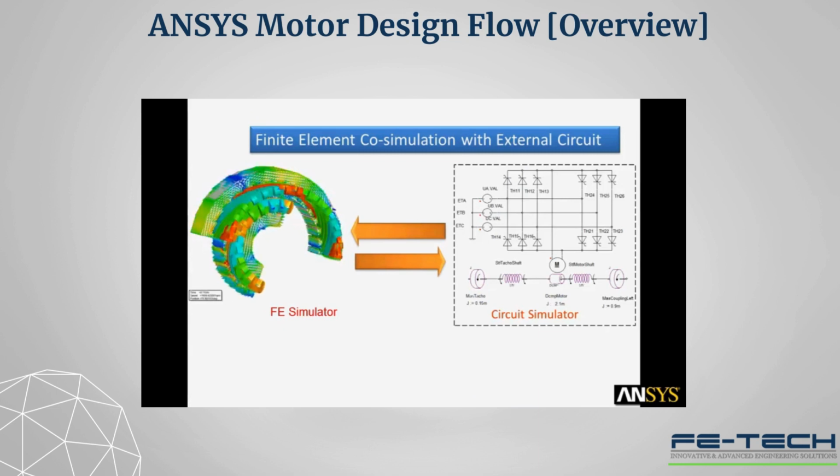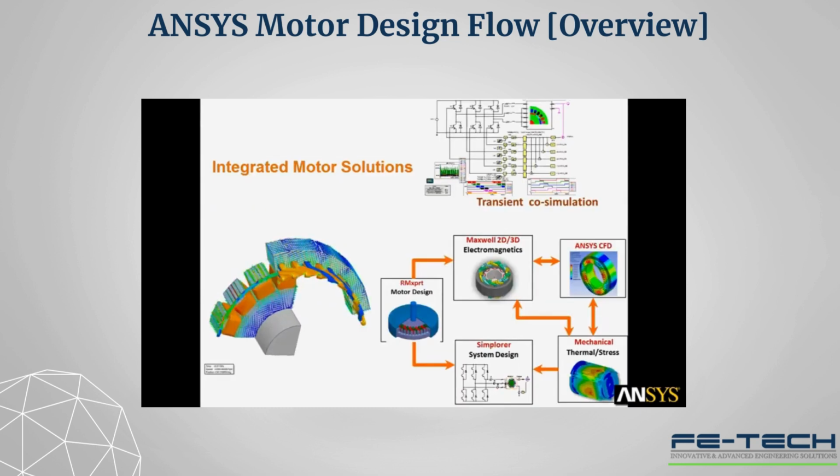Electric machines require appropriate electric drive circuits. Maxwell finite element analysis co-simulates with the Simplorer circuit simulator to evaluate how nonlinear behavior of the motor affects the drive circuit and vice versa. Ansys tools allow you to simulate complete integrated motor behavior by linking physics and systems solutions. RMxprt provides the initial motor design and 2D and 3D models. Maxwell performs 2D and 3D electromagnetics analysis. Ansys CFD and Ansys Mechanical are used for thermal and mechanical stress, and Simplorer ties all the physics together in a top-level system for drive circuits and other behavioral components.